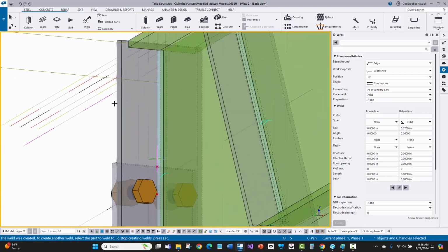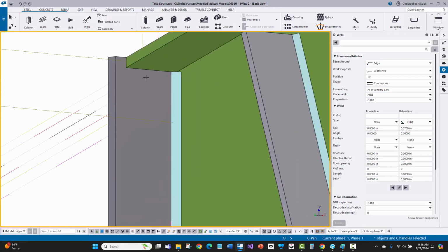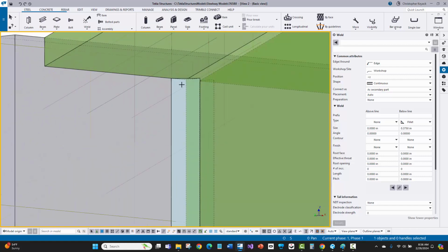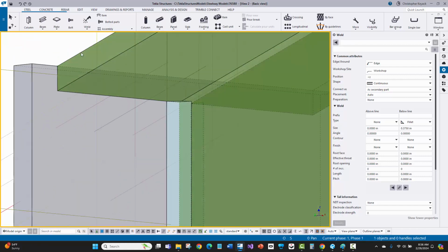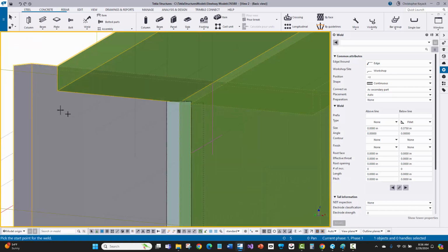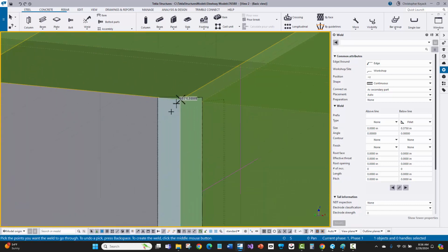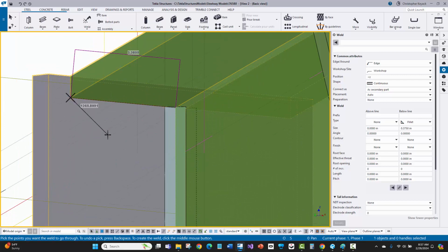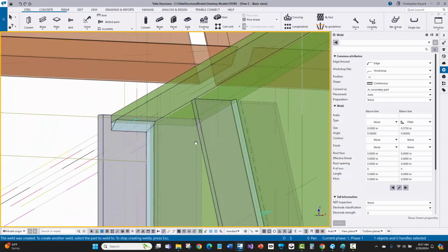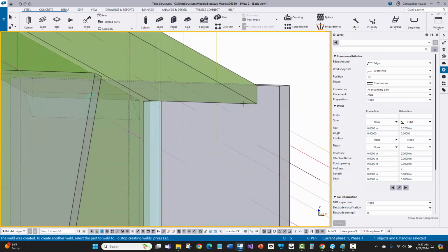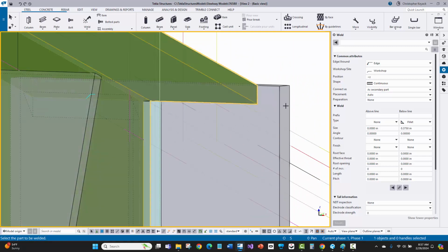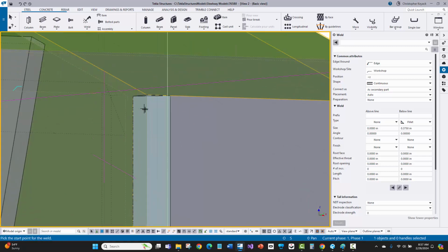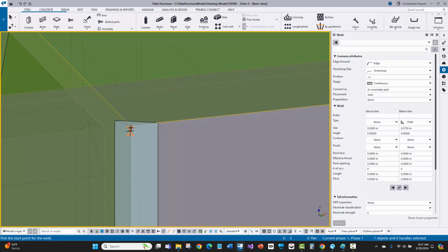And then really you just rinse and repeat this process. So I'm going to do the weld up here. I did Control-2 to get into transparent. If I'm in transparent, I have to click near the edge of the material. So I'll click on that beam, then the end plate. And now I've got that corner point. So that's 0.1, 0.2, middle mouse button. And again, you just rotate around and repeat the process. So here's my next weld. Pick on the beam, pick on my plate. And then I can just come in here and make sure I find the right corners.